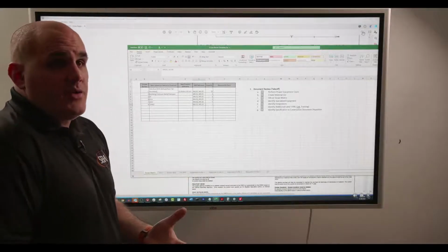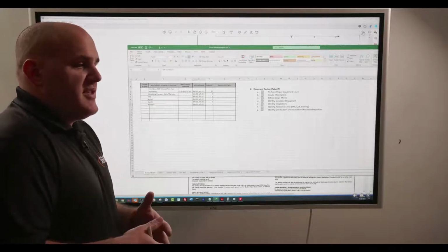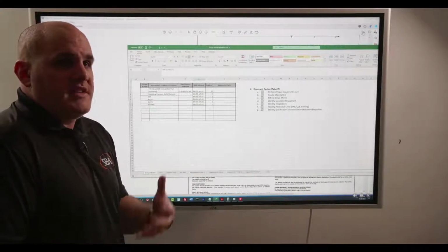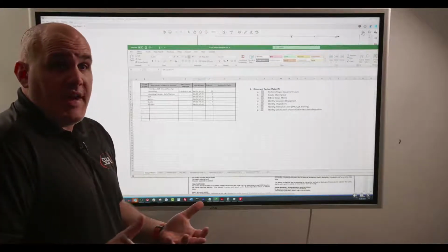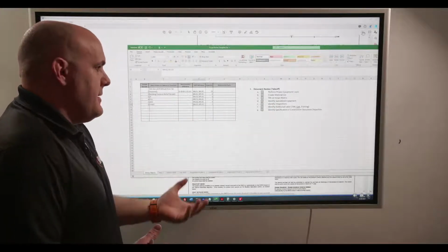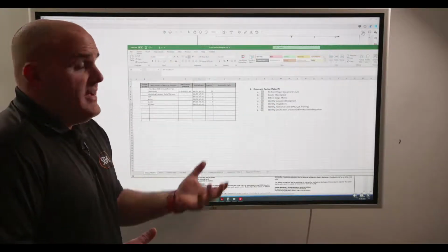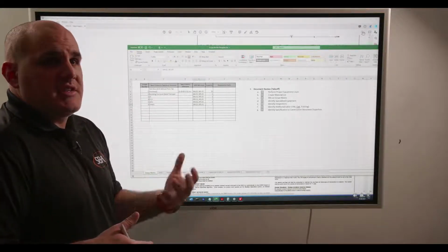So any sort of specialized equipment that I'm dealing with that potentially poses risk. These are things like humidifiers, dehumidifiers, enthalpy wheels, heat recovery chillers, etc. Right? So you got that. And then I'm also going to identify any integrations. That's typically going to be called out in the spec. And so that will be my BACnet chiller integrations, lighting integrations, etc.